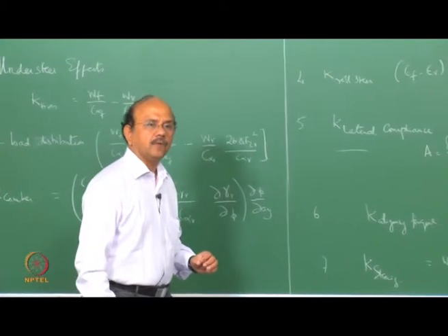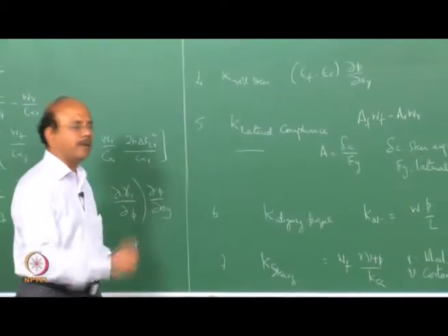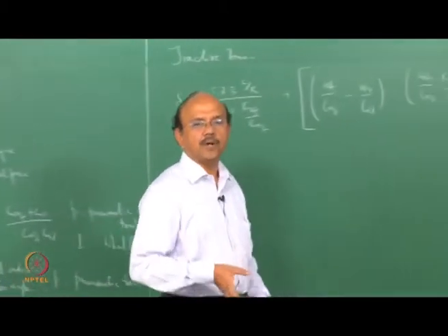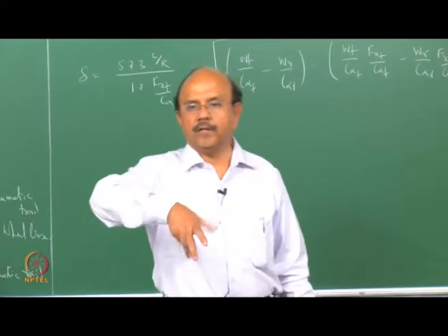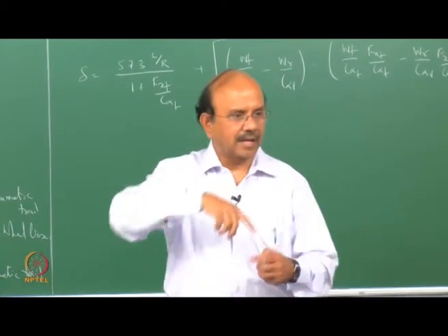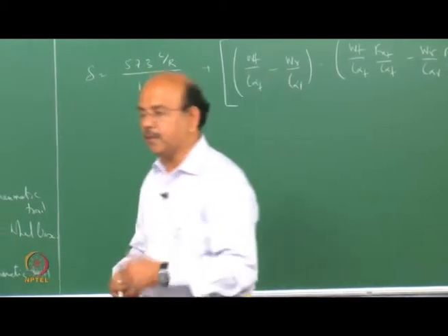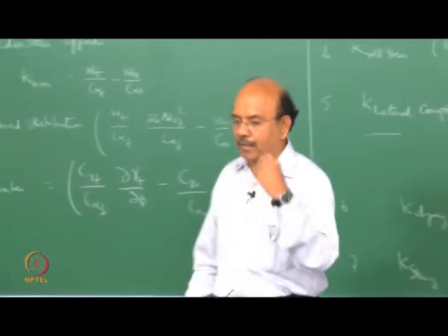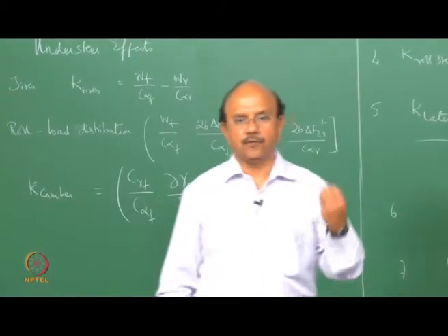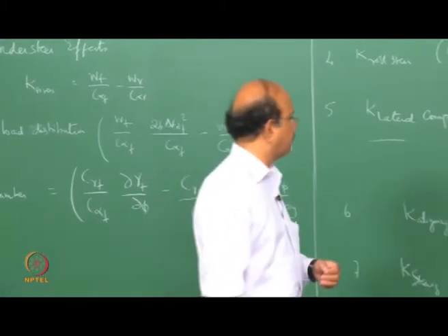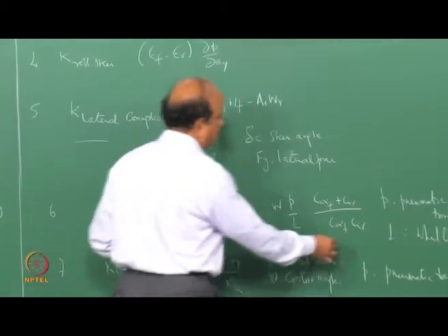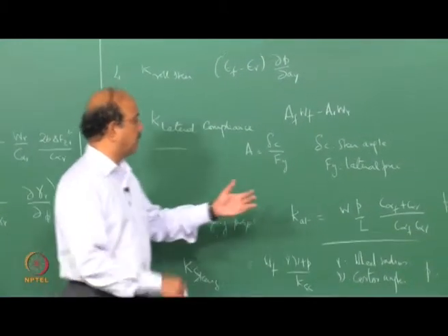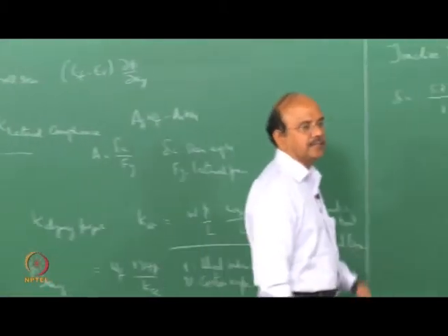Obviously we made a comment at the end of the class. We will come back to the comment. Obviously, aligning torque will have an effect. After all, aligning torque is what makes the vehicle go straight. It aligns the wheel, so anything which has an effect on the wheel will also have an effect. So aligning torque has an effect on the understeer gradient, and the aligning torque value is given by this, where P is the pneumatic trail, L is the wheelbase, and so on.